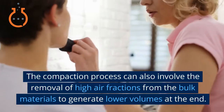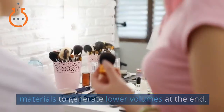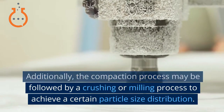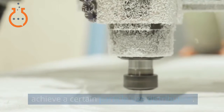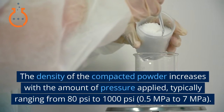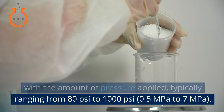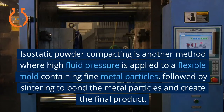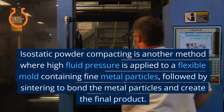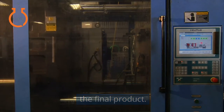The compaction process can also involve the removal of high air fractions from the bulk materials to generate lower volumes at the end. Additionally, the compaction process may be followed by a crushing or milling process to achieve a certain particle size distribution. The density of the compacted powder increases with the amount of pressure applied, typically ranging from 80 psi to 1000 psi, 0.5 megapascals to 7 megapascals. Isostatic powder compacting is another method where high fluid pressure is applied to a flexible mold containing fine metal particles, followed by sintering to bond the metal particles and create the final product.